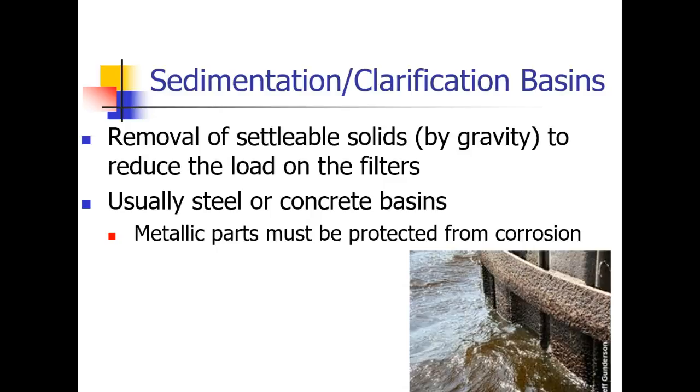Sedimentation and clarification basins: the removal of settleable solids by gravity to reduce the load on the filters. Again, the more stuff we can get out before it hits the filters, the better off we are. They're usually steel or concrete basins, and the metallic parts must be protected from corrosion. You know, corrosion is a big deal in this industry. We have very, very expensive infrastructure.